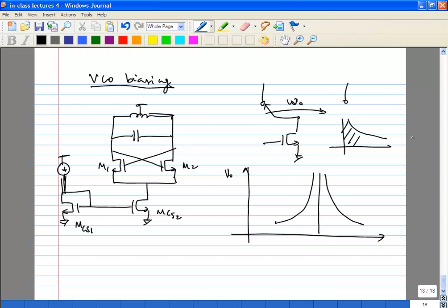So part of the flicker noise in this region comes from the bias transistor. Now the next question is, we are analyzing it like a mixer. So let's say this is which current? Tail current is constant, but along with it you also have a flicker noise, right? So that flicker noise also gets multiplied with this omega naught switch between the two paths.